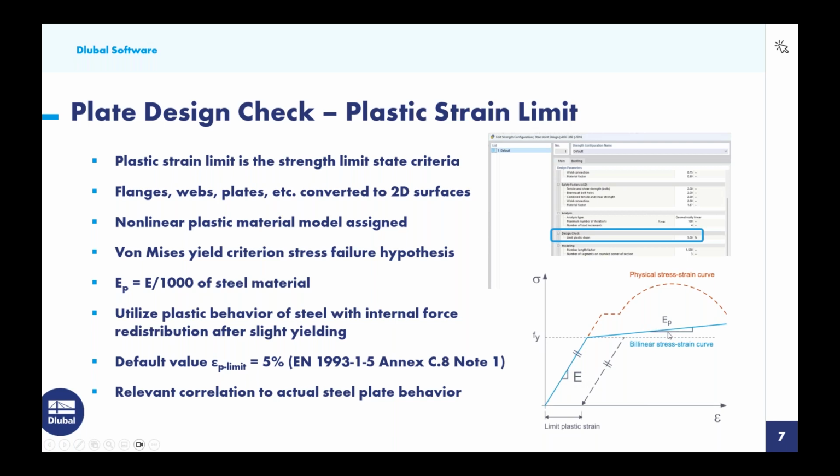But in the plastic region, we assign a plastic modulus of elasticity, which is going to be the linear elastic modulus of elasticity over 1,000. So this is just a simplification that we take with that nonlinear plastic material model.